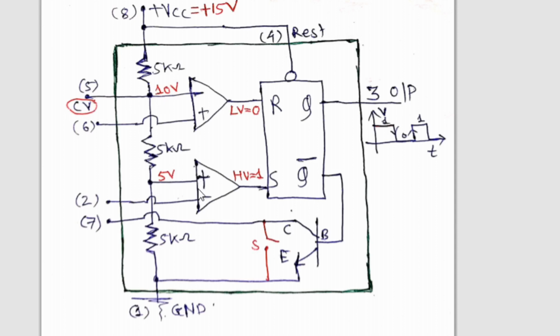As we have drawn the lower comparator in front of the gap between R2 and R3, the junction is connected straightaway to the lower comparator's terminal, and we know that the lower comparator is drawn such that the upper terminal has the positive sign, that is non-inverting.